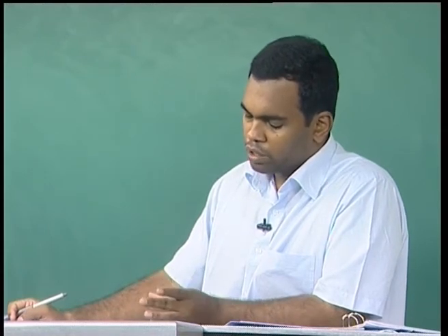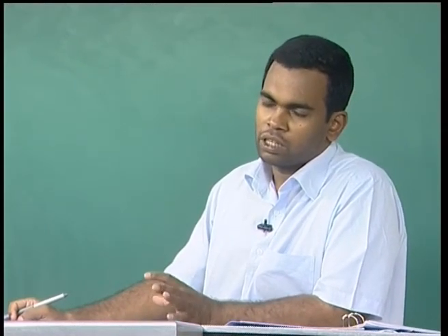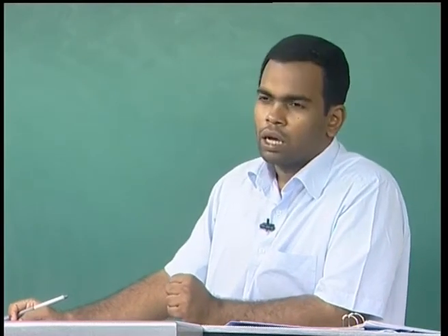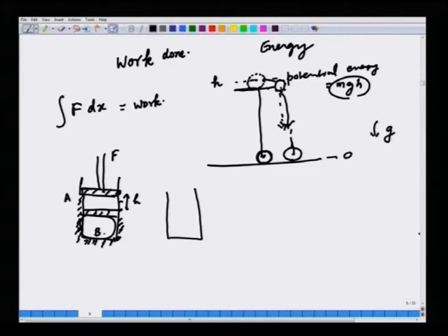Now, in state B also, once you have done work and given some time for the gas to settle, the gas will be static. So, what has changed from state A to state B? What has changed is the internal energy of the system. This is a new concept, it is not there in mechanics, it is the concept that comes from thermodynamics. Internal energy of a gas or a fluid in general is that part of energy that is stored in the molecular degrees of freedom of the fluid.